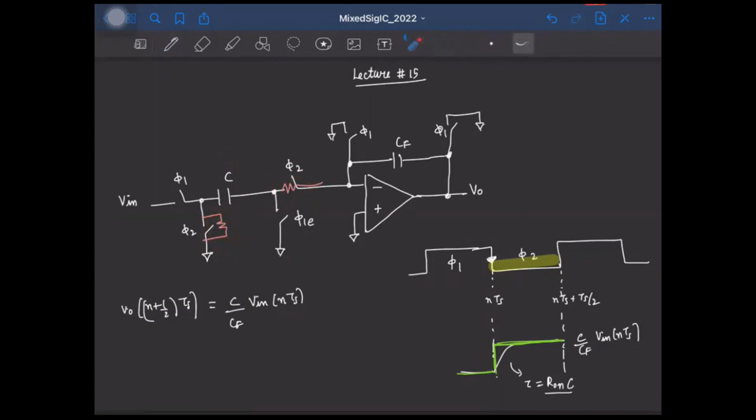In this, we know how to implement each of these switches. So let's now see what to do about the OpAmp here. Please notice that the OpAmp, as we have considered here, is an ideal voltage controlled voltage source. That is, it has an infinite input impedance and a zero output impedance. So let's see what are the possible candidates for this OpAmp.